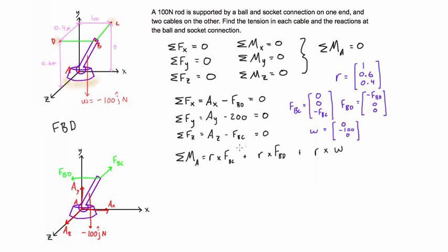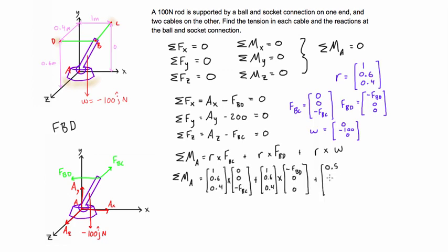Alright, so anyways, moving on, what we want to do is we'll just expand this out. So we'll have our position vector cross our force for each of these. And you'll notice here the first 2 position vectors are the same because their lines of action are intersecting the same point that we're measuring the position vector from A to. And here we're seeing that the position vector for the weight is half because the weight happens at the mass center, and so that's halfway along this beam, and so all the measurements here are taken in half.